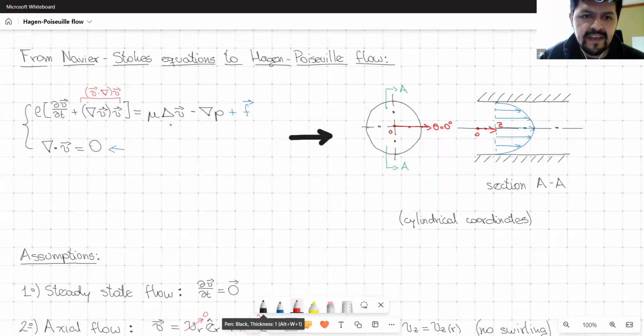Whereas on the right-hand side, we'll take the three terms that we generally have in this type of problem, namely the viscosity-associated term, the pressure term, and the one associated with so-called body forces, which typically come from the weight of the material we're considering.